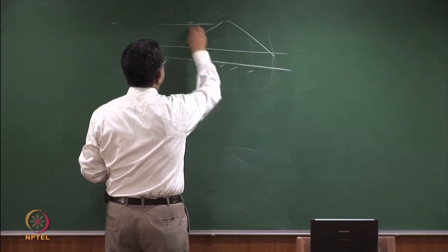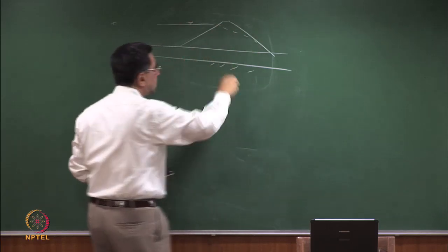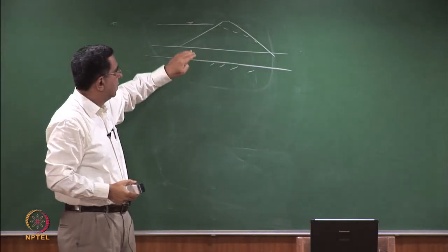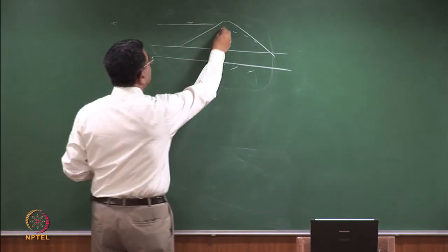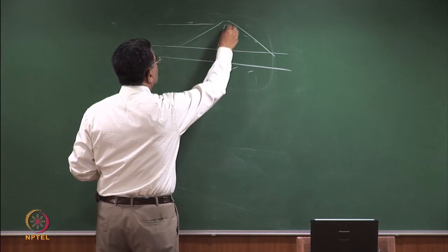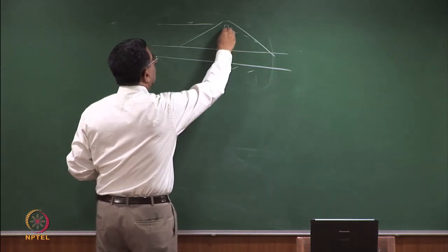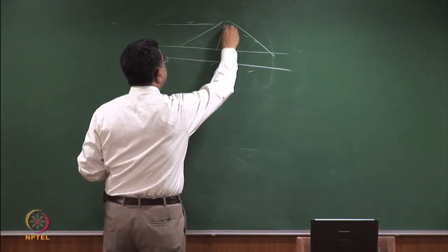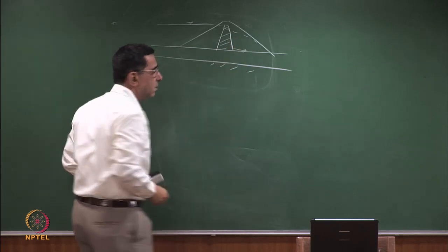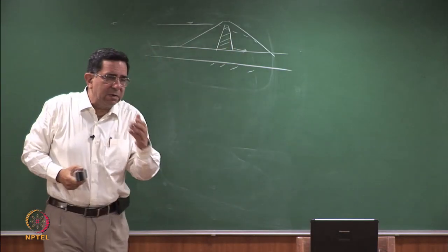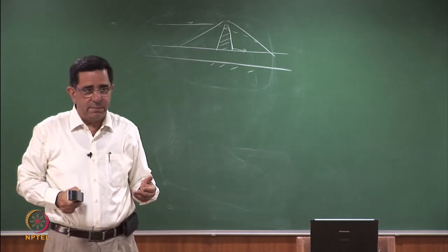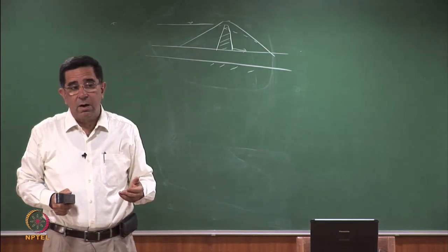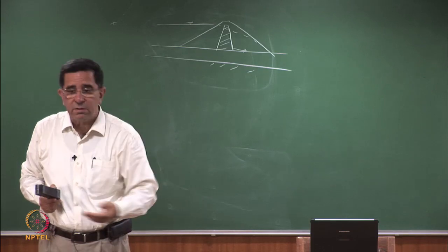So why I'm bothered about seepage through the dam and also seepage beneath it if this is pervious. So in the dam, to prevent seepage, I put a core, a clay core, right? And this line disappears, it comes here now. So we've been dealing with this for many years. What do we do below the dam if it's got a pervious bed? How do we prevent the seepage from going from beneath the dam?